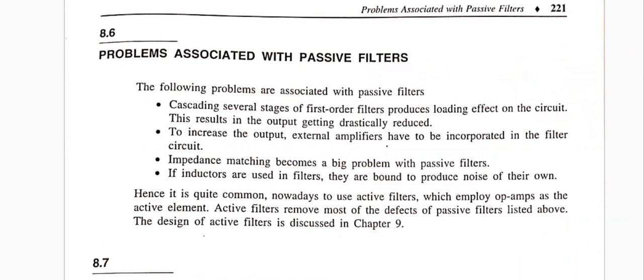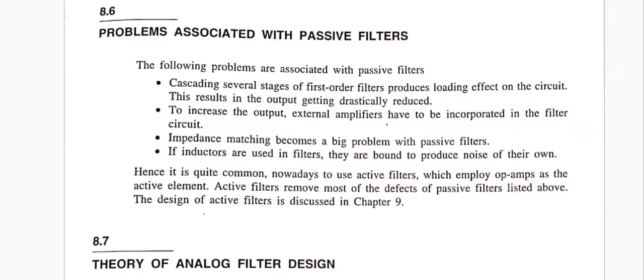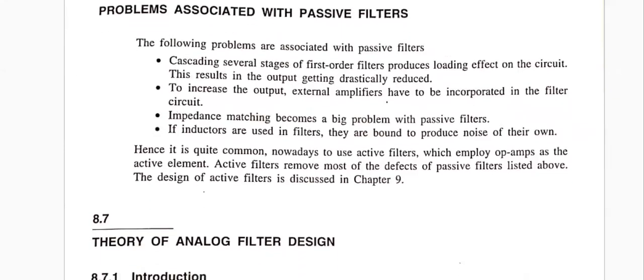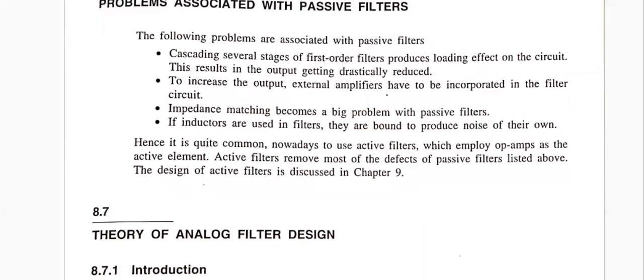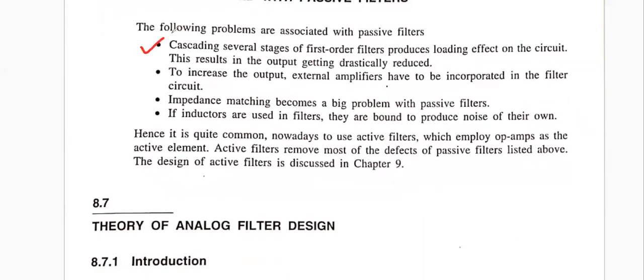So why shouldn't we use passive elements or passive filters for filtering? I believe that you have these ideas. Just to recall, whenever we cascade several stages of first order filters, it produces a loading effect on the circuit, and this results in the output being drastically reduced. So you know that this term is very important, the loading effect.